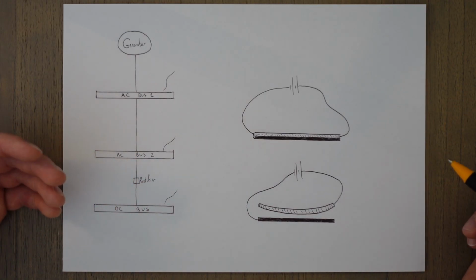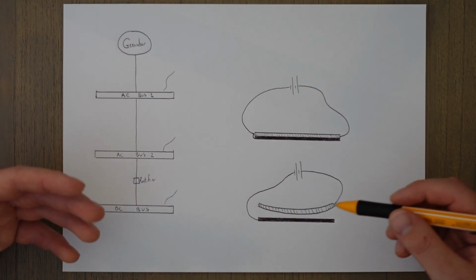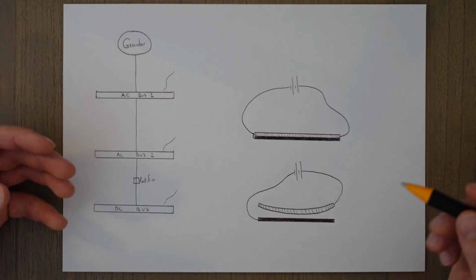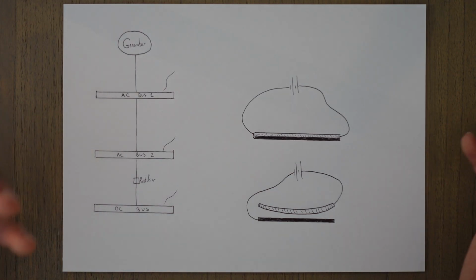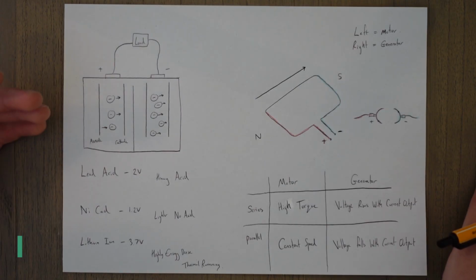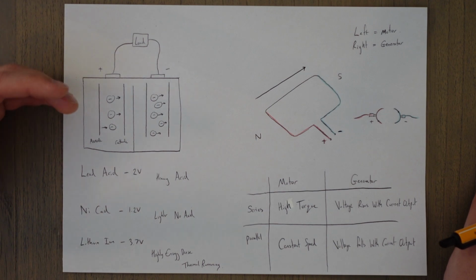It also helps if you have problems on the ground that are pretty minor. You can reboot the system by popping the circuit breakers and then resetting them, basically giving it the old on and off again treatment like we do to our computers at home. In summary then, a battery uses two plates of a material in some sort of liquid or gel solution.